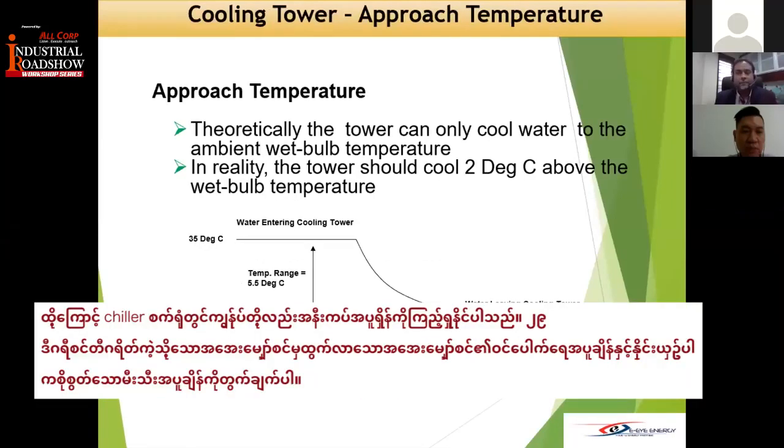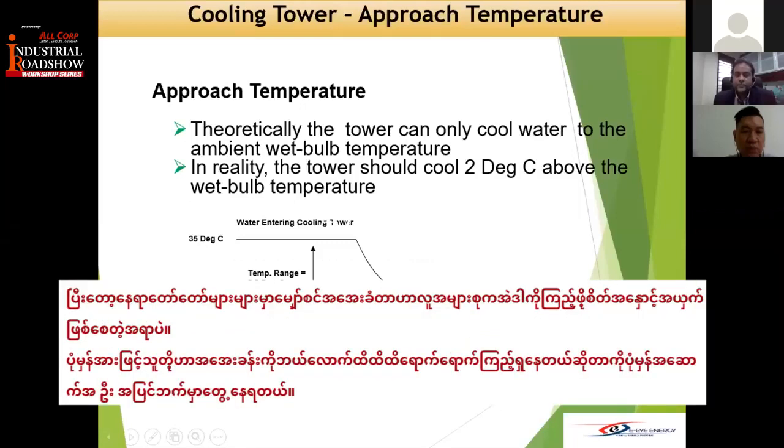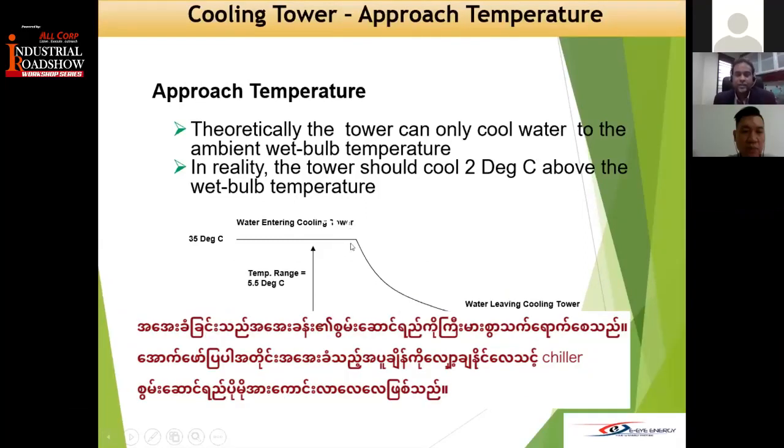So on the chiller plant, we also can look into the approach temperature, right? Approach temperature is a wet bulb temperature against this inlet water temperature of the cooling tower, which is coming out from cooling tower, which is like over here is like 29 degrees C, which is coming out. And you see in most of the places, right, cooling tower is something that is not many people bothered to look at it, because it's an outside of the building, and normally they are just looking the chiller, how efficient the chiller. But you see, cooling tower brings a big impact to the efficiency of the chiller.